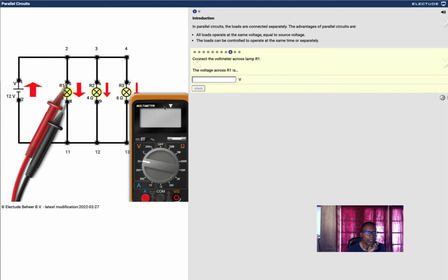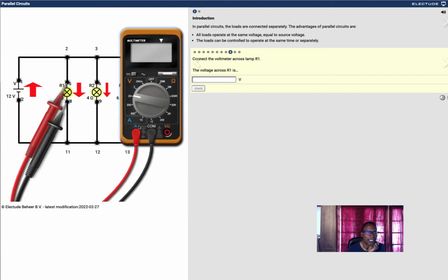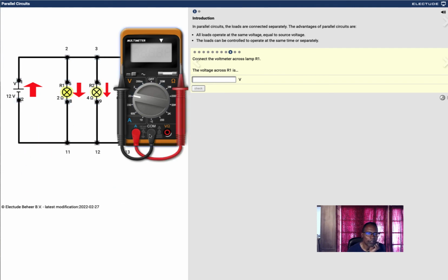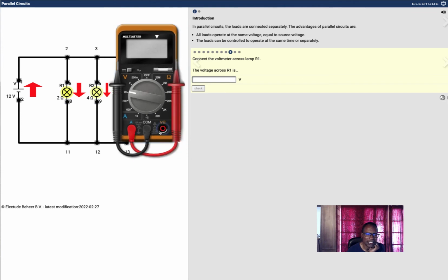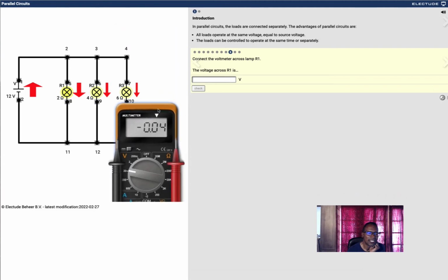Oops. Oh no, I blew a fuse. See? I never moved it over. That's an amateur mistake. You can always move it over when you're done with the meter. This is why most fuses are blown in the shop. I didn't move it over. Let's try that again.